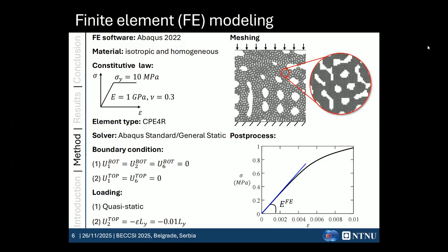And here is how we post-process our data. We get the stress-strain curves, and we extract the linear response in order to get the effective stiffness from the finite element simulations.